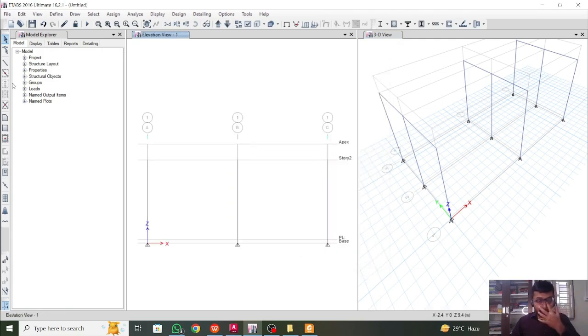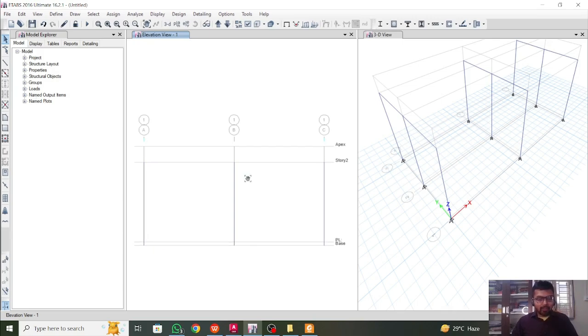So for this roof truss, you can go with angle sections here, I sections, ISMB sections also. We can go. Let's try ISMB 300 here. I can try the lower side also, but let's try that later.